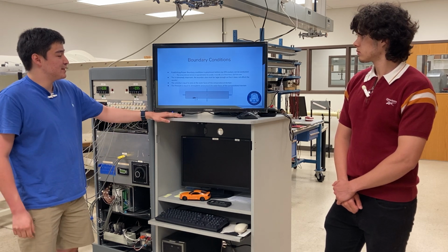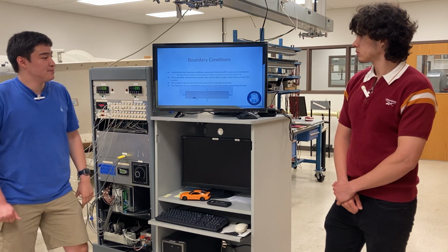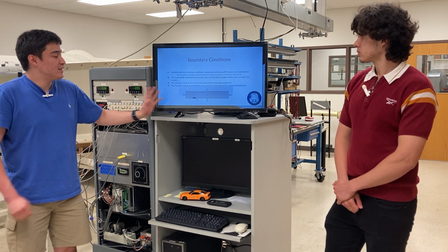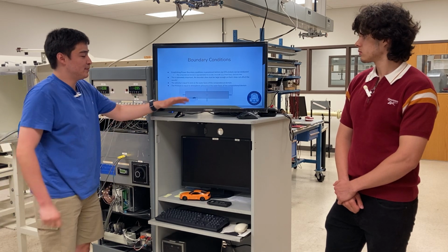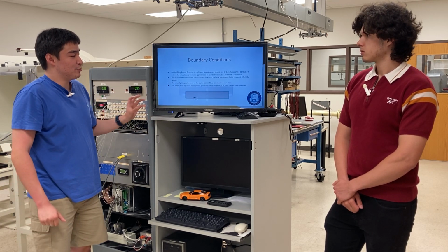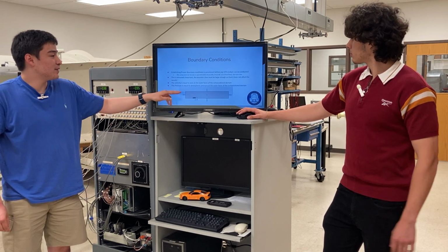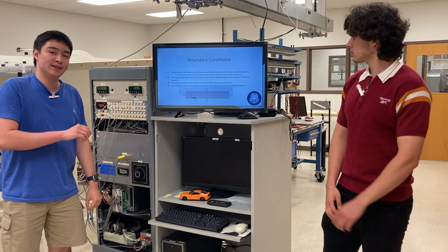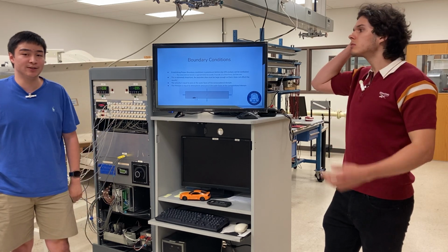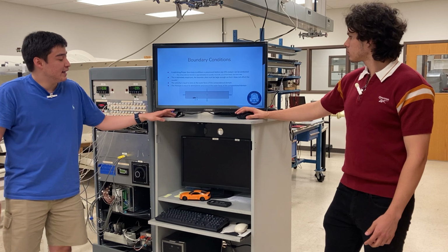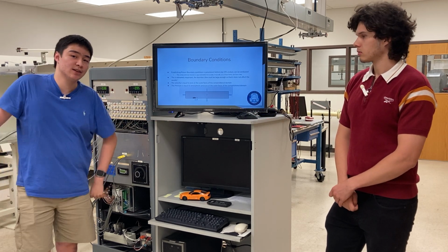So what we ended up doing is for the computational domain, it's roughly 5 times as wide, 5 times as tall, and 15 times as long as the truck from the rear. Having it extra long in the rear is the most important, because then we can watch the velocity profile eventually go to 0. For this domain, on the outer surfaces of the domain, the pressure is equal to atmospheric pressure and the velocity is equal to 0. And we're assuming a no-slip boundary condition on the outside of the truck.